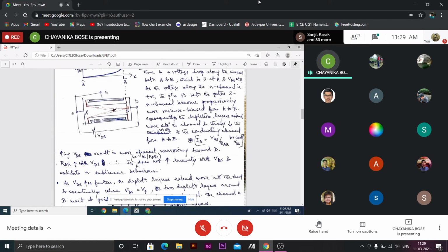And over this will be superimposed this non-linear variation appearing due to this longitudinal field. And at this drain voltage of 3 volt, pinch off takes place at the drain end. Now if we increase the drain voltage, say it is now 4 volt, then at an earlier point the reverse bias is -5. Drain voltage is now 4 volt, but here drain voltage is 3 volt and it is at -2.